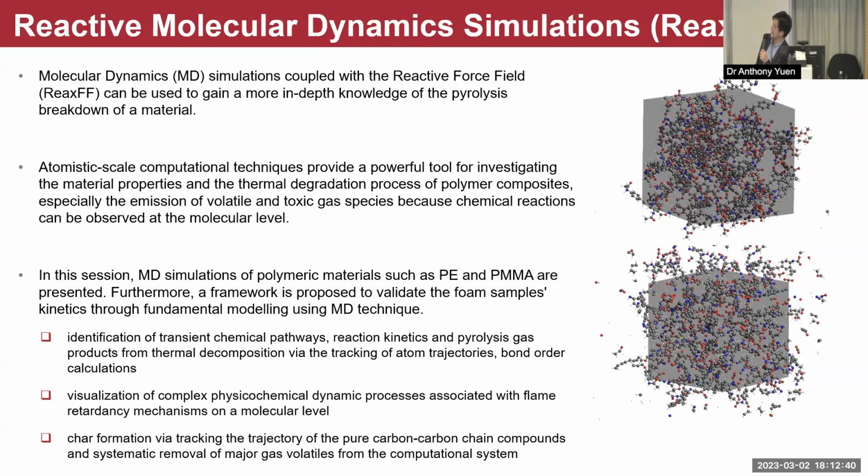We build a molecular structure in a cube type of way, and then we add heat into the control volume, and then we see how the molecule breaks down on the right-hand side. So in this section, we are going to give you a brief understanding by having a benchmark study on polyethylene and PMMA, utilizing this MD technique. We will mention how to characterize the degradation rate of this molecule.